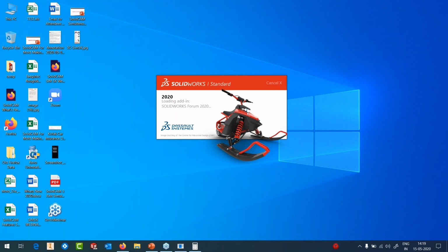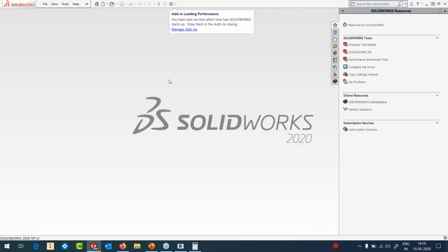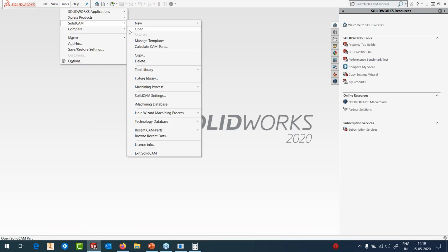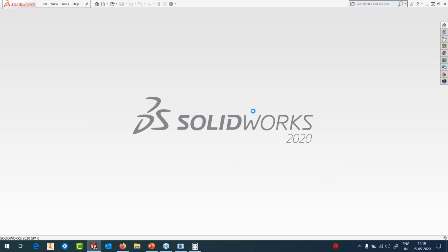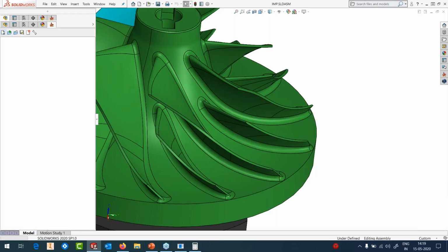Okay, again, some people have asked a very valid question on impellers, I think, because they have got this experience of buckling of the blades, especially after you've done the finishing. When you remove the part, put it on the faceplate and allow it to age for, let's say, a day, and then you take it to the CMM, it shows a completely different picture of the blade. The blades would have buckled.